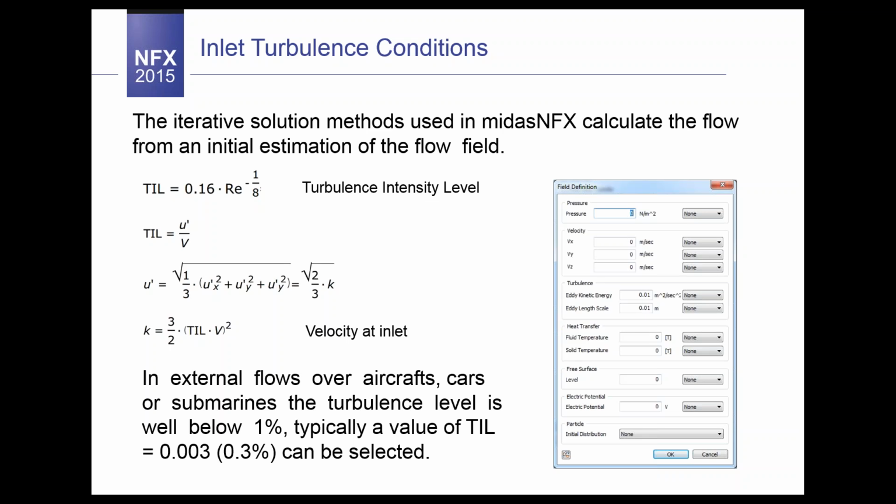The next step refers to the turbulence conditions, inlet turbulence conditions, or even initial conditions. There is a need to estimate some quantities like turbulent intensity level. In some codes you can define this with the inlet definition, but in midas NFX you simply go to the analysis case window and you can find the field definition. So we are treating this as the initial condition.